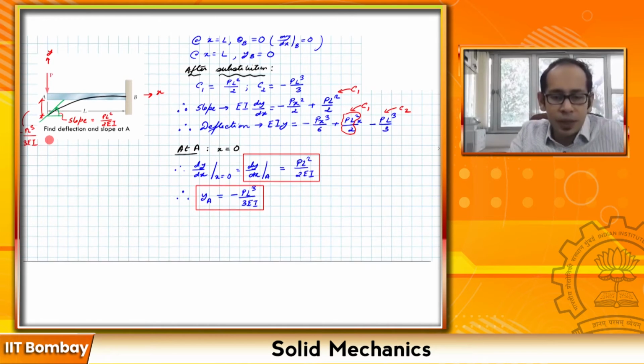Now, one thing you would also want to check is that when you have these deflections, you can plug back the units of E, I, L cube. So you will see that this expression goes to the order of mm or inches or so on. And you should also plug back into the expression of the slope, to find the units of the rotation that you get over here, right? So I hope this problem example was clear. So in this one, we looked at a cantilever beam with a load at the tip. Let's go ahead and look at the second example.